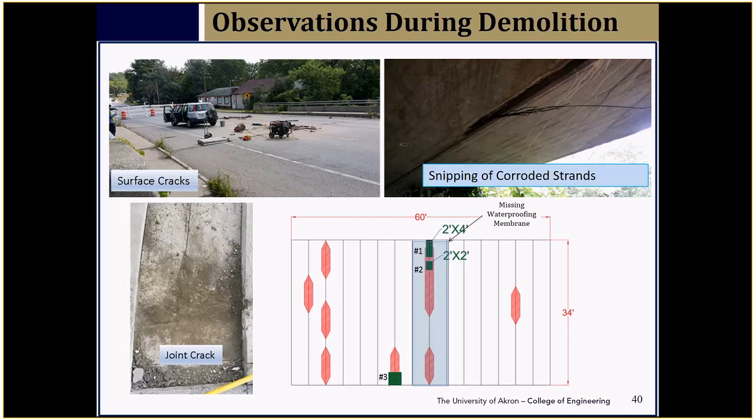It's not the paver. The paver is fine because you're putting asphalt and it's very hard, so you just roll it. That's probably distributing the load over a larger area. Whereas driving a roller on bare membrane with grit or any aggregate particles will actually make the membrane totally porous. That's what is happening.